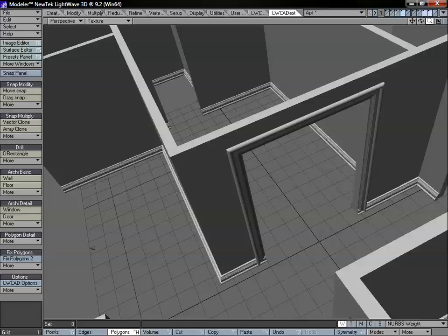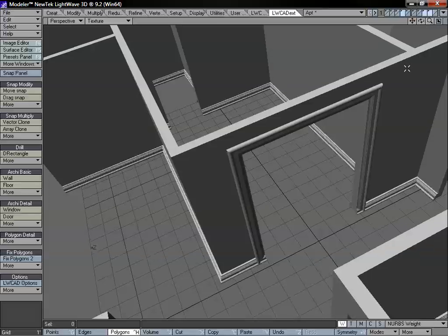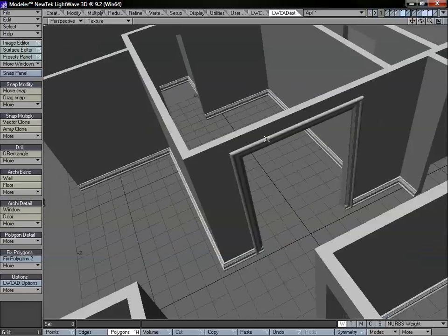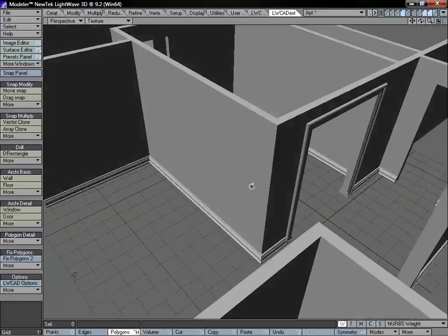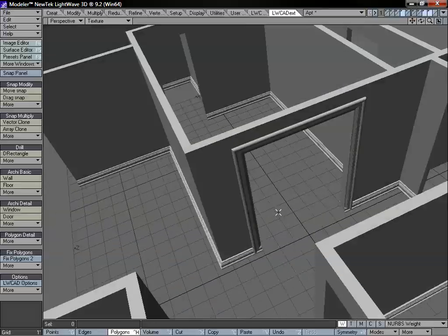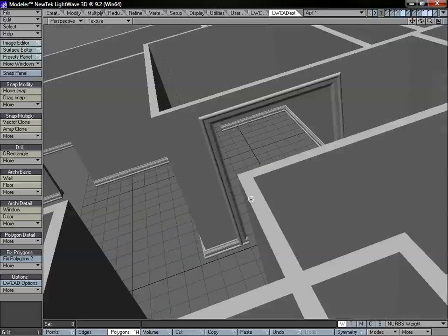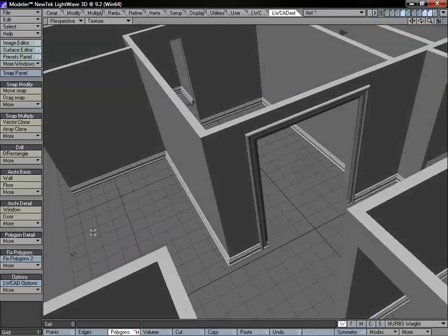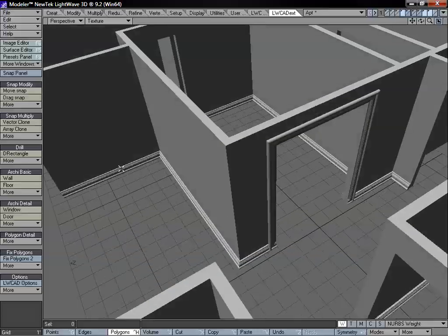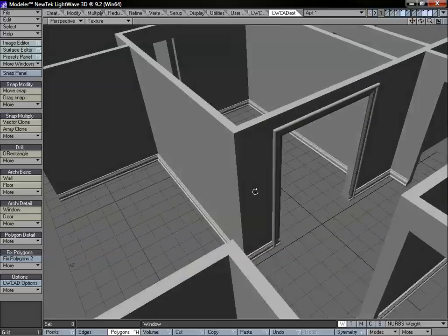We could also join those together, but it would be really quite difficult to do that since they are facing the other directions, and mainly because they really are going to have different points in different places, and doing that would be somewhat difficult. But if I was to initially create the entire trim in this room by creating one polyline, in this case, what I would do is select from over here, and then this point, the next point down, and then over to here, and then select these points up here, move along, and then of course if I needed to go along some of the other areas, I would select those as well.